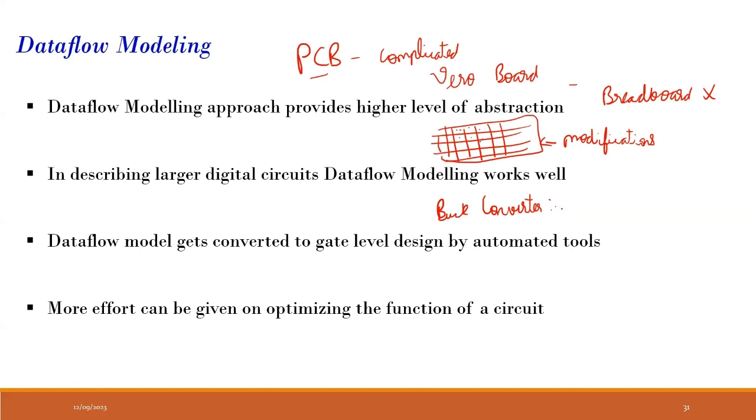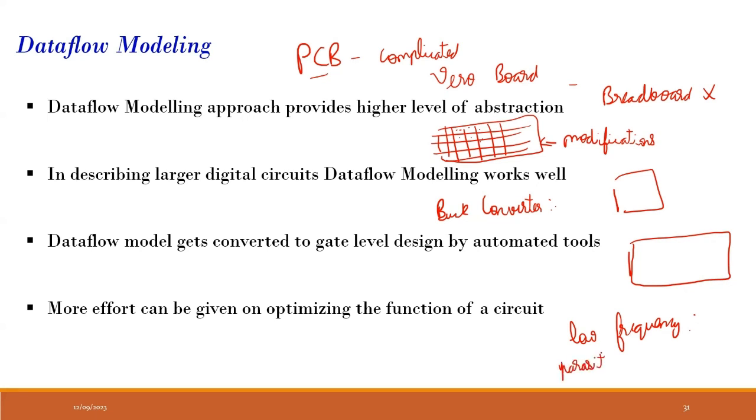Make a simple buck converter with simple current sensing, which we taught earlier. You don't need to make it very compact; you can make it big. And you can run the converter at low frequency, so the effects of parasitics will be minimal. That is what I would advise.